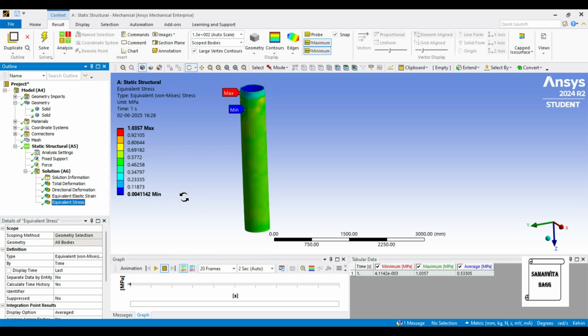Now, what is the advantage of using CFST column? We have also analyzed a circular concrete column, and here we are seeing the column which is of steel material and it is filled with concrete. When you use only concrete, concrete has a lesser value of yield. Here the load is shared by the steel and the concrete material both. Also, the yielding of this column will be much slower as compared to a complete concrete column.